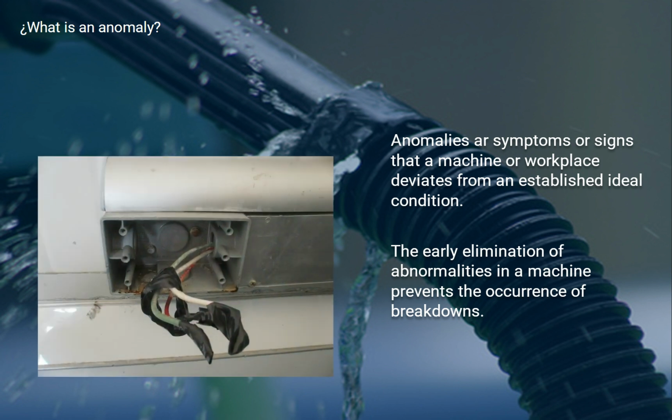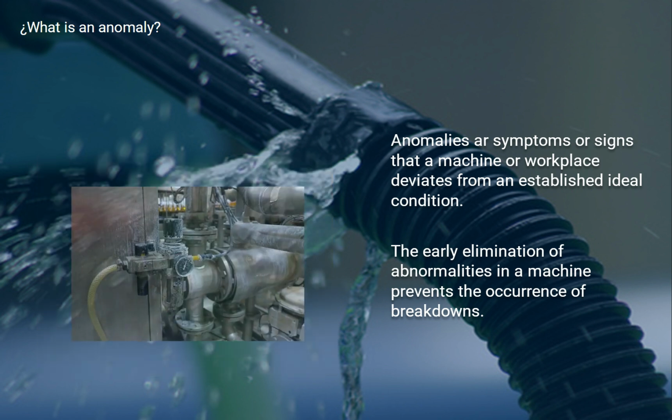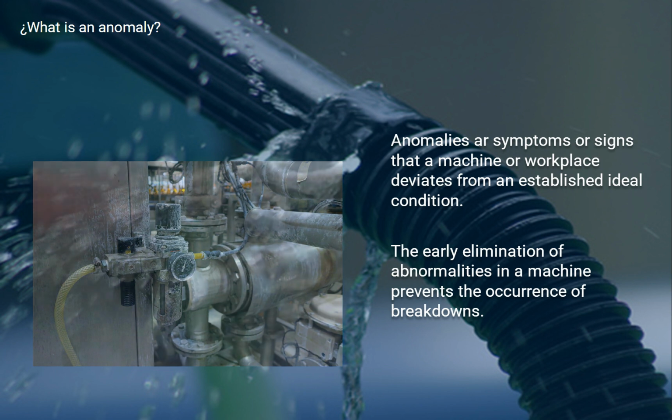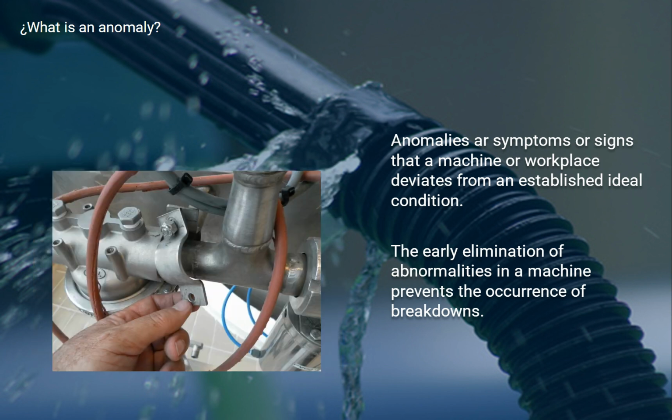During the initial phase of autonomous maintenance, especially in the initial steps, the focus is on performing thorough inspections of equipment to detect and correct as many anomalies as possible. This effort constitutes the first line of defense against breakdowns and serious machinery problems. An effective practice in autonomous maintenance involves establishing databases that facilitate the tracking and analysis of the troubleshooting process. It is crucial to avoid mixing information on breakdowns, process failures, and anomalies in these databases. Later in this unit, we will go into more detail on this topic.